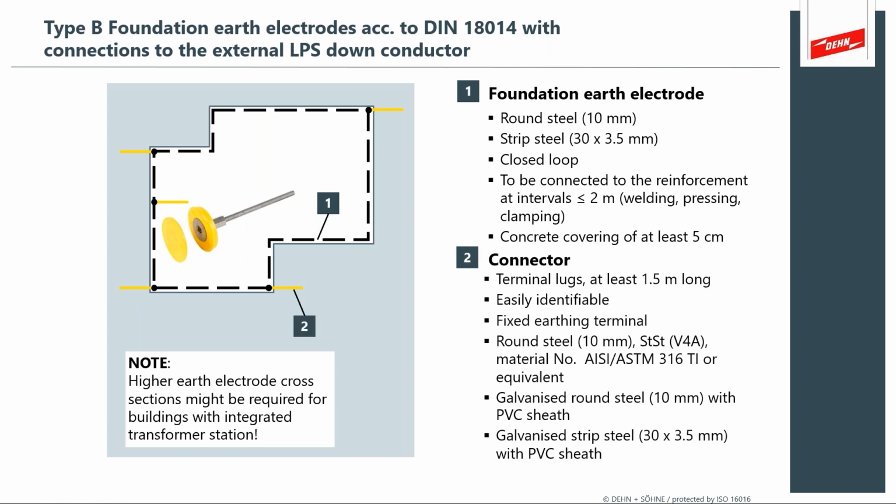There's a lot of guidance in the standard, what that should look like, the types of materials. You want to be inert, you don't want to have rusting, and you want to avoid things like dissimilar metals that will cause accelerated corrosion. So again, using the guidance of the standard will get you a long way.